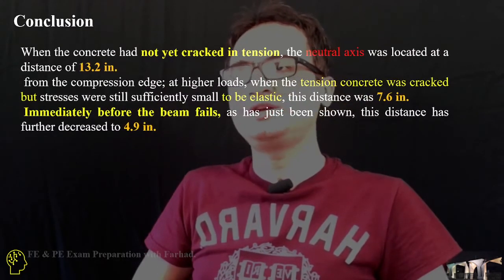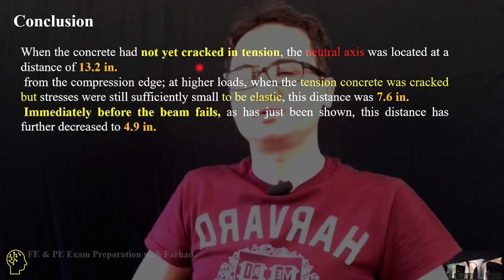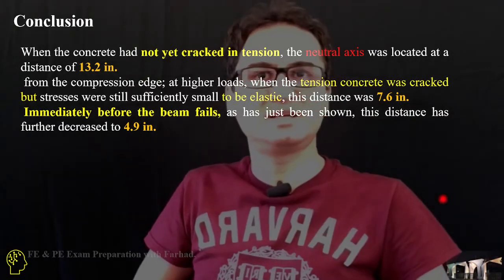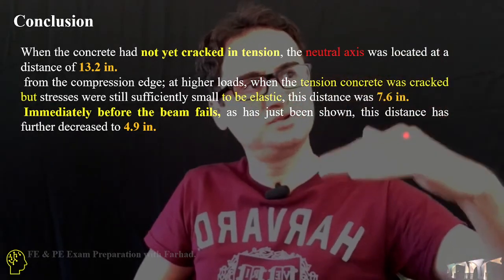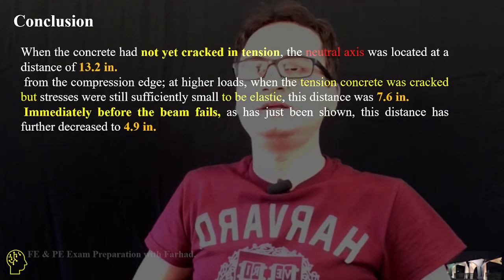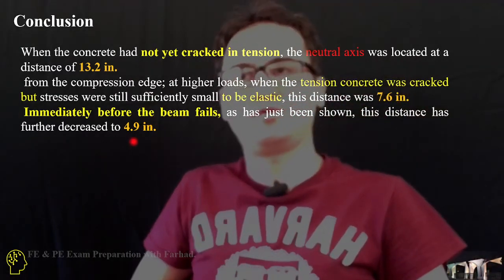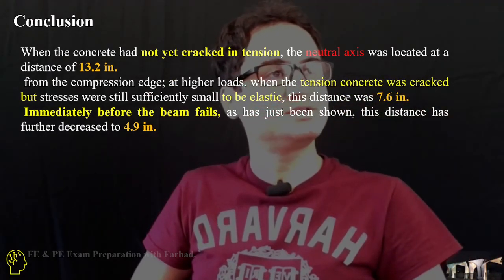So as a conclusion, when the concrete had not yet cracked in tension, the neutral axis was located at a distance of 13.2 inches. As the section cracked, but the steel is still elastic, it moved a bit higher to 7.6 inches, the distance from the top edge to the neutral axis. And immediately before the beam fails, it traveled upward farther to reach 4.9 inches in terms of the distance from the neutral axis to the top edge.